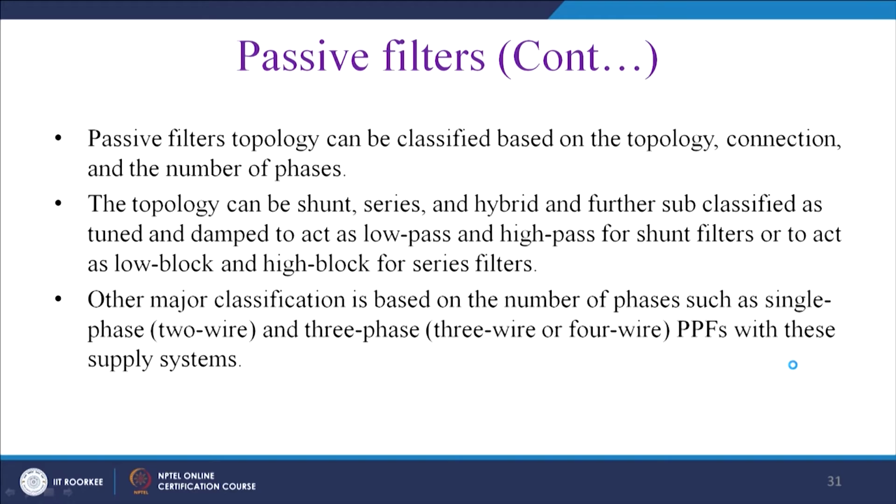Passive filter topologies can be classified based on the different kinds of connections and number of phases. The topology can be shunt, series and hybrid, and further subclassified as tuned or damped, acting as a low pass filter or high pass filter for shunt filters, or as a low block or high block for series filters. We shall see the details in the discussions.